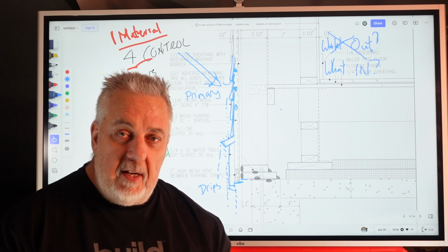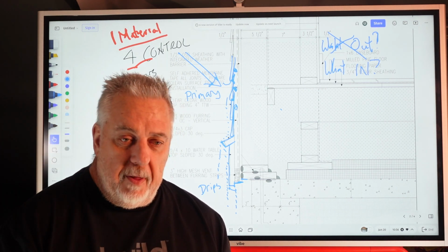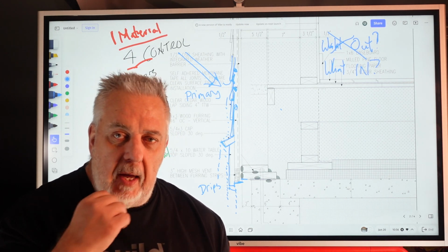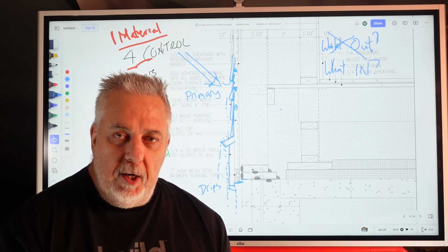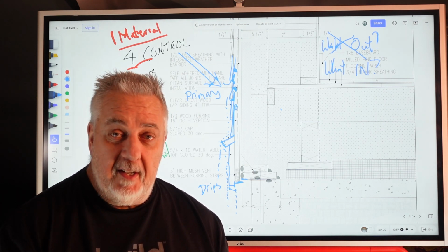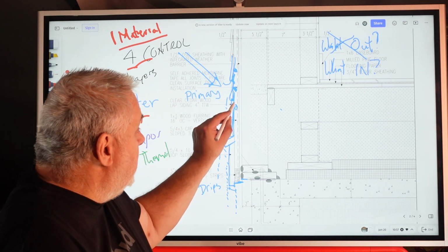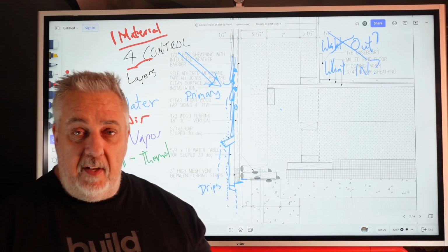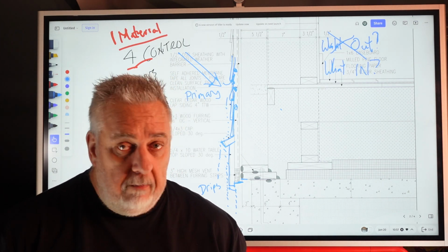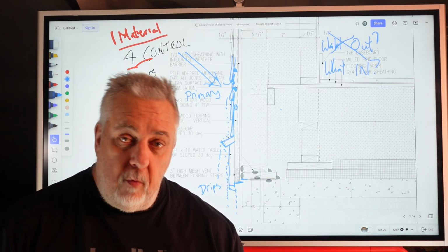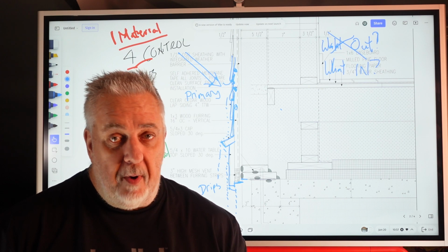So the minute I put sealant on the building, some people think in their mind, hey, I'm sealing up the building, I'm keeping all the water and moisture out. When what you're really doing is you're sealing stuff in. Now, here's another way to look at it. If I put a bead of sealant there and it successfully keeps the water out, okay, it's done its job. No harm, no foul. If water gets in and can't get out, then I have a major problem.